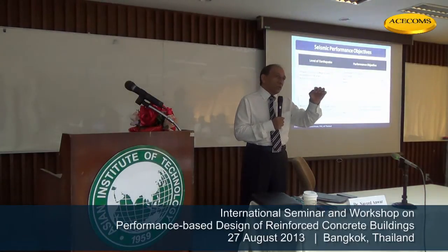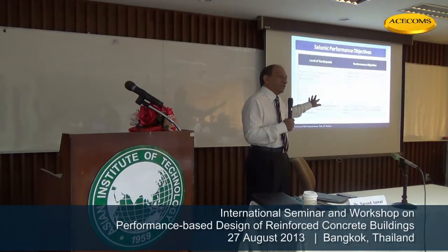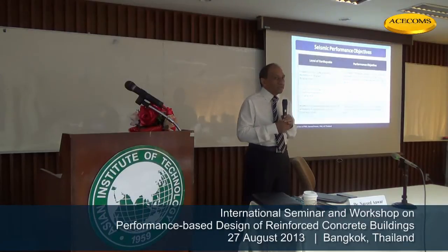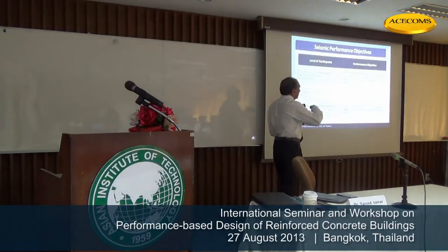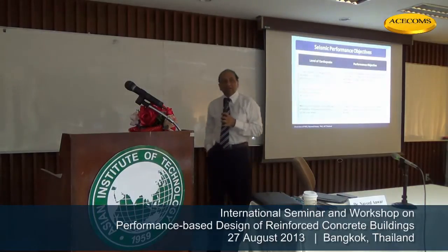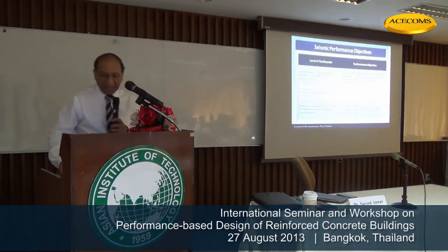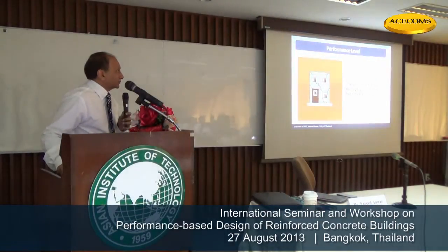So the consequence of not conforming can be built into the selection of the performance indicators and the level of earthquake. So that is how we can adjust what we want. The client, the public, and other people can agree what performance we need for different levels of earthquake, and that's what makes performance-based design interesting, because it lets other people come in and make the decision.